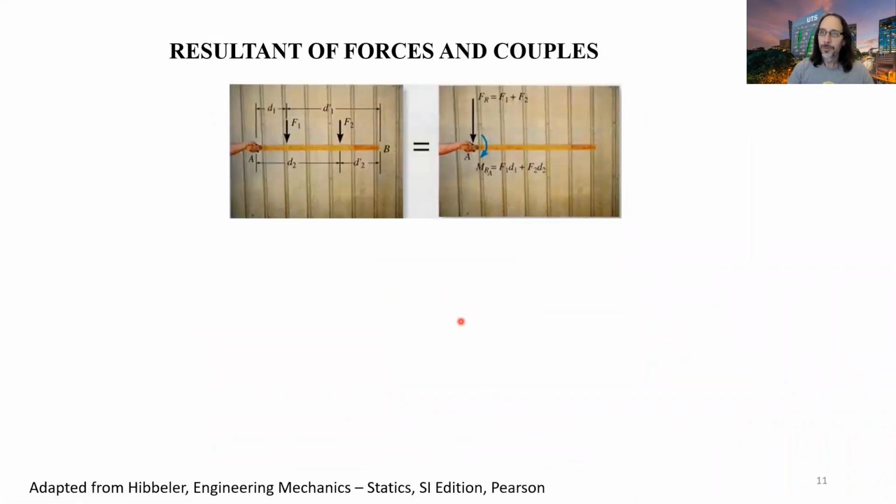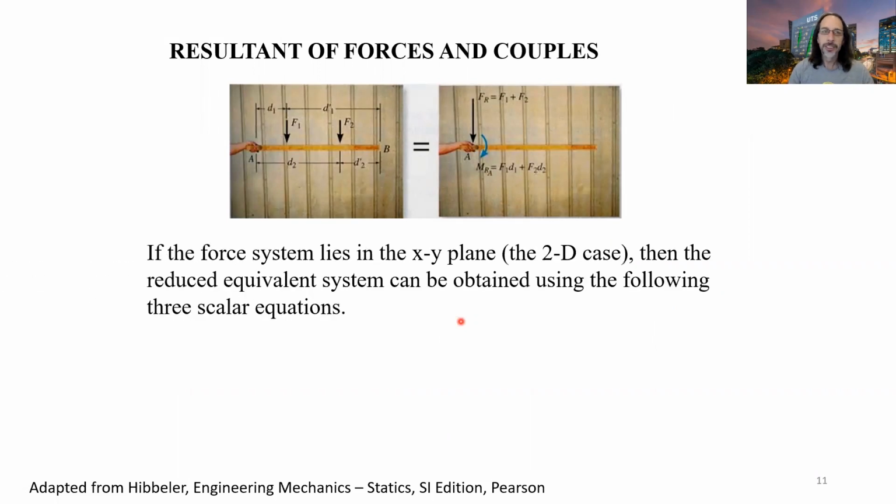All right, so from the textbook, if you've got more than one force, the process is just more of the same. So here, if you want to find the equivalent force and moment at point A, at the hand support here, we've got two forces, F1 and F2. We just sum up all of those moment effects of each of those forces. So we just use the scalar equations. So we've got the two forces. In this case, we've only got forces acting vertically downwards.